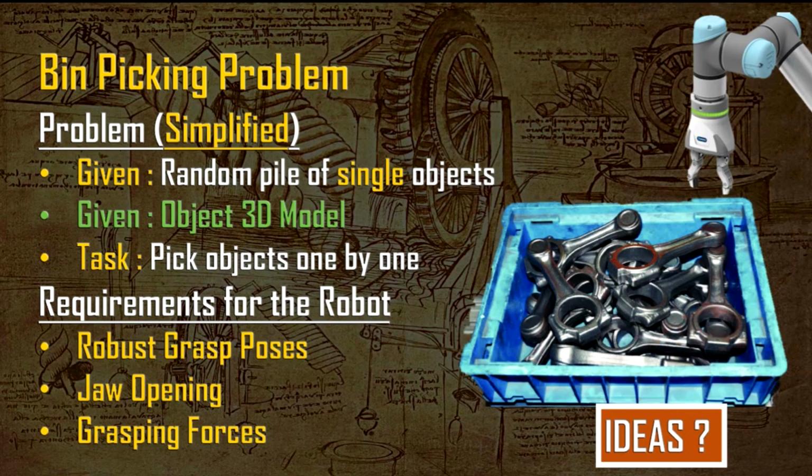That means that in this position, the robot is exactly at 90 degrees in front of one of the details. It doesn't matter which one. And we know the diameter of the circle from a distance, let's say half a meter. We know the diameter of the circle in the taken picture, and with the comparison, we can calculate the distance between the camera and the circle. That gives us the distance from the robot to the part. I don't know if I explained it well.